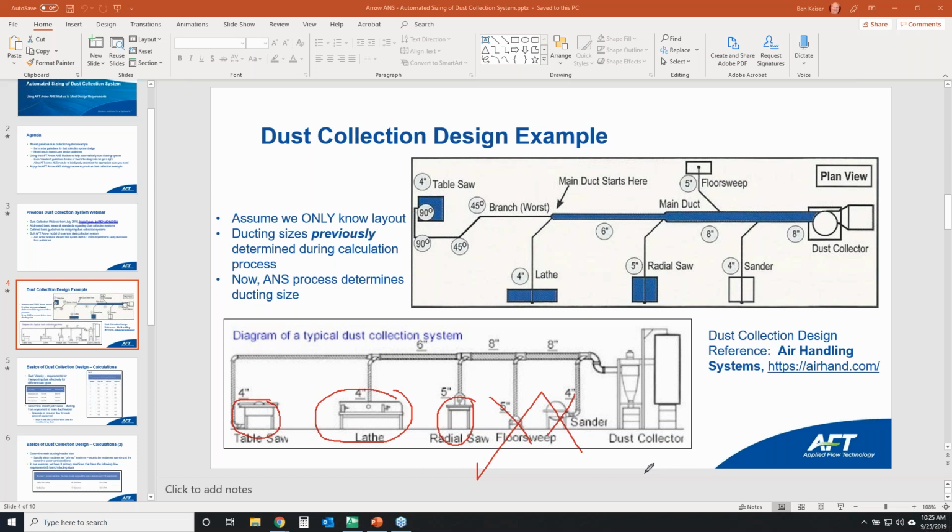So this is another major downfall to these rules of thumb: they dramatically oversimplify the process of what's actually happening. Who's to say that it's guaranteed that these two pieces of equipment are always going to be turned off when the rest of these are running? So when you're designing your system, you want to design for the case where you need the maximum amount of flow. That way, if you had the maximum amount of flow going on, then at least your design requirements would be able to be met in those cases.